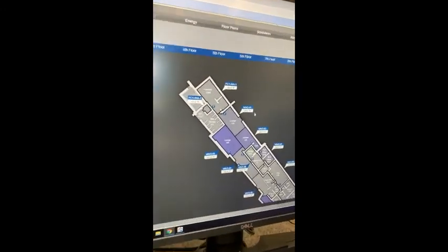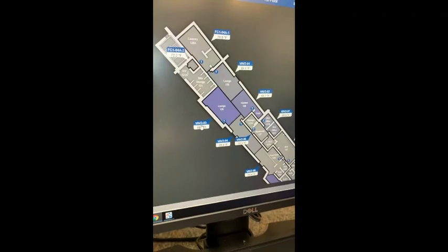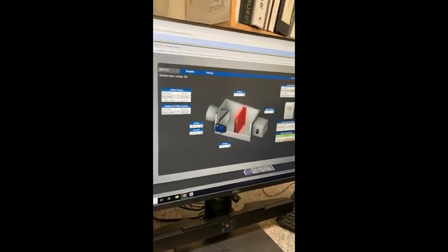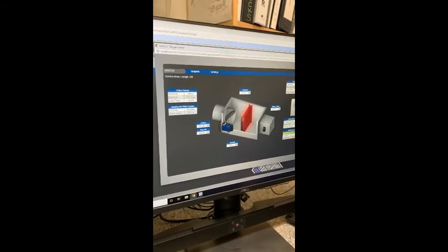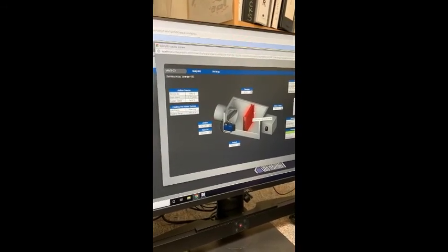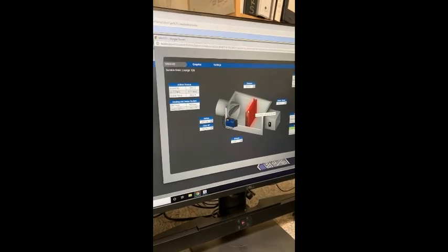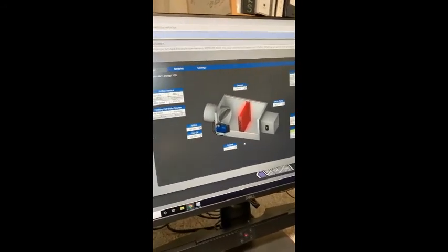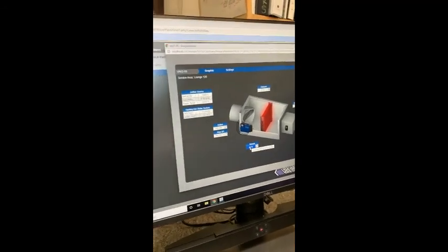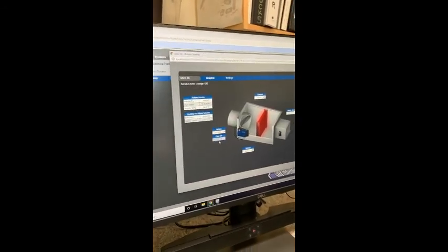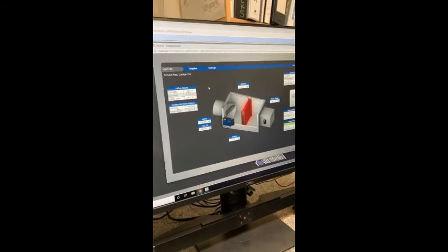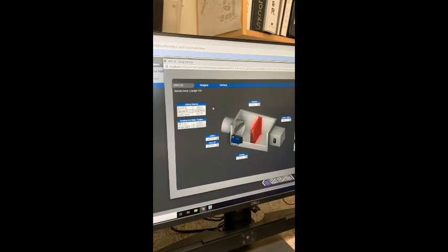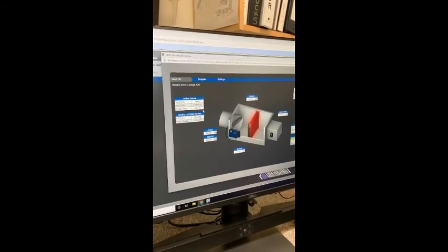And then from here you can individually select a unit and click and pop up. I'll show you. We can see that this unit here, this VAV, is actively heating, so the coil is showing that radiant glow. We can see our discharge air temp here. We can see what the valve reheat command is, how much airflow command versus set point. And then it does list the unit that it's served by and what its status currently is.